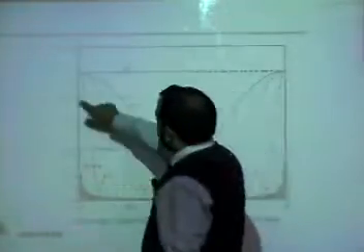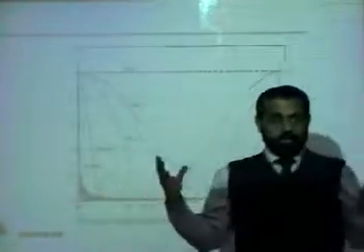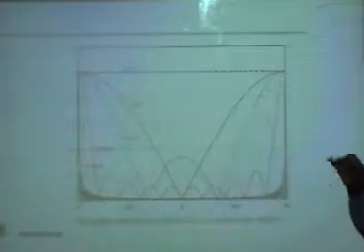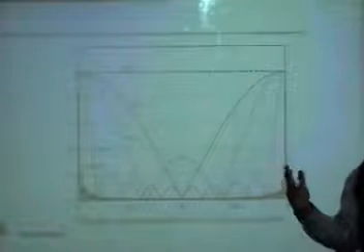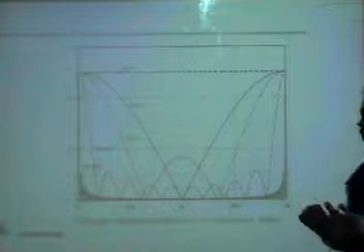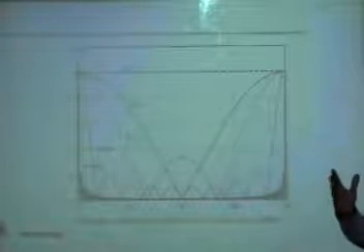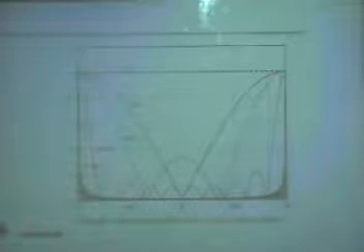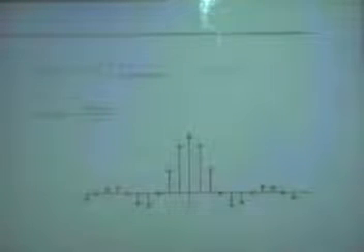That's what you see. If you increase the number of points in the moving average filter, it will be just a DC value. It will eat up all the frequency contents, obviously. So the averaging is that if you have a higher averaging filter, it is going to eat up all the frequency contents in the signal.